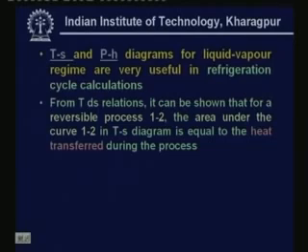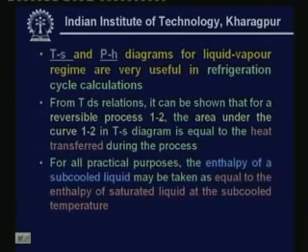So if you can plot the process on the TS diagram, and if you can measure the area under the curve 1, 2, then you have the heat transfer during the process. This is very, very useful. And for all practical purposes, as I mentioned just now, the enthalpy of subcooled liquid may be taken as equal to the enthalpy of saturated liquid at the subcooled temperature.